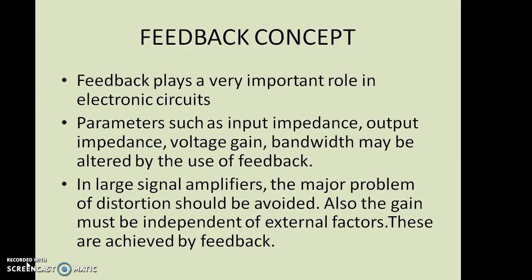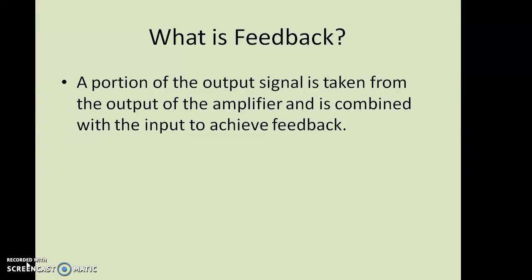In large signal amplifiers, the major problem of distortion should be avoided. Also, the gain must be independent of external factors. These are achieved by feedback. So what is feedback? A portion of the output signal is taken from the output of the amplifier and is combined with the input to achieve feedback.